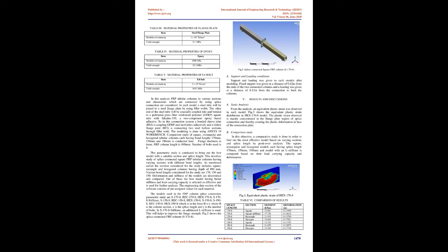This data section consists of pre-assigned values for each material. Poisson's ratio and density used for each material are 0.3 and 7,850 kg per cubic meter respectively. Sikadur 330 adhesive was used as the epoxy material. The material properties given for the model are shown in the below tables.